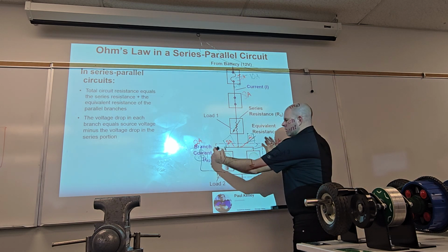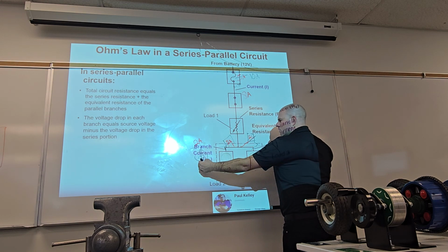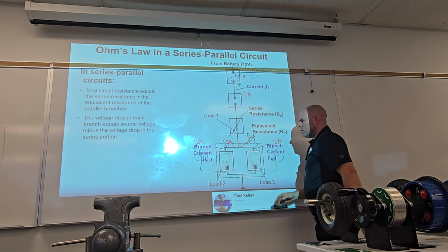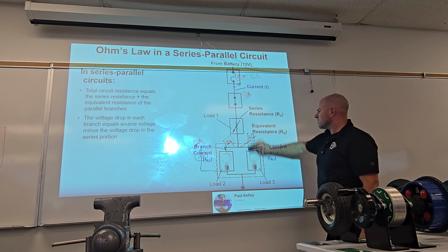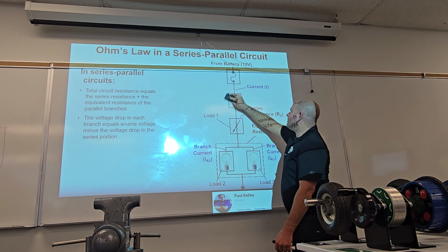There's going to be some number of amperage at the individual legs, and the total of all the individual legs is always going to equal the series section. The only difference is we add a load, but that doesn't change our measurements really. So it's not real complicated.